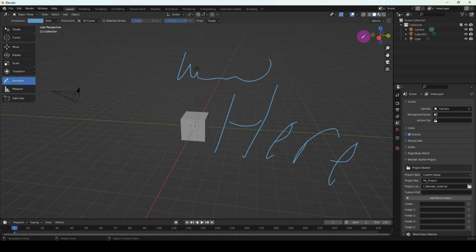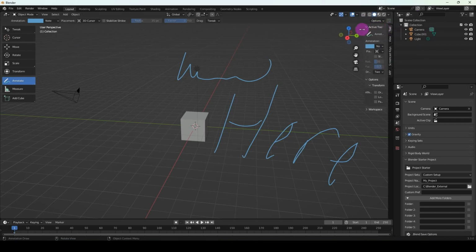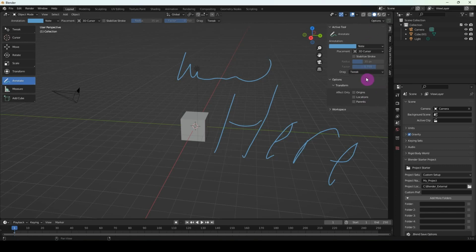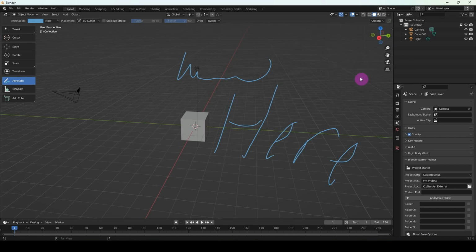If you look over here to the right, you will see an arrow that is pointing towards the left. That's a very small arrow. If you left click and drag that out, you'll be presented with another menu. Alternatively, if you press the N key, it will hide and unhide that menu. And to hide and unhide the tools menu, you would select the T key. So that's T to hide it and T to unhide it. So for the left side, T; for the right side, N.